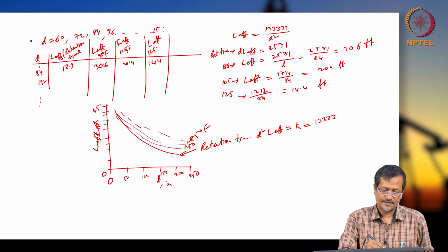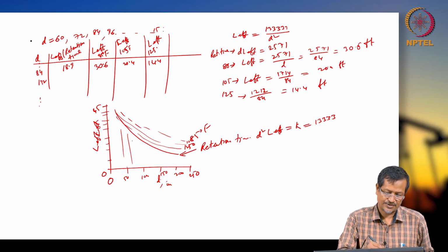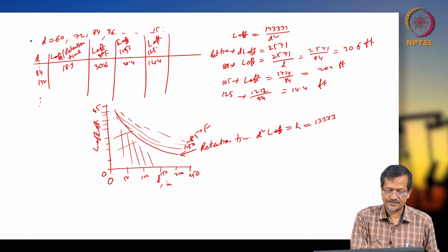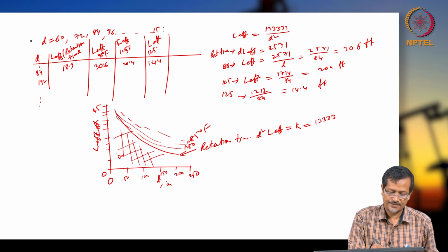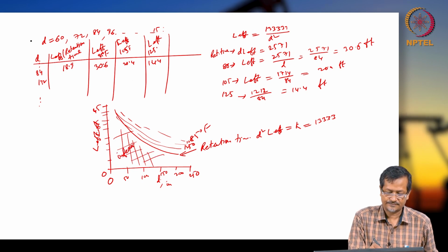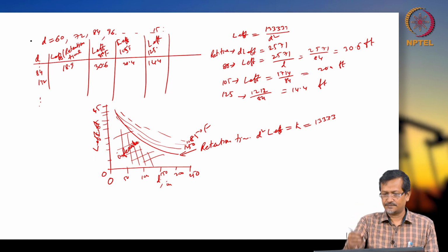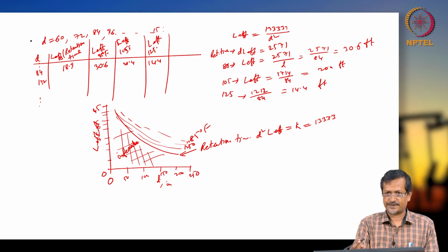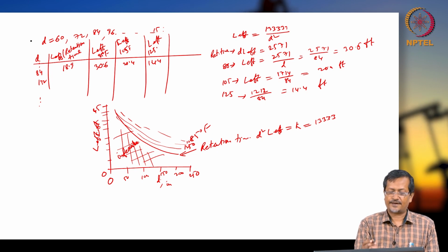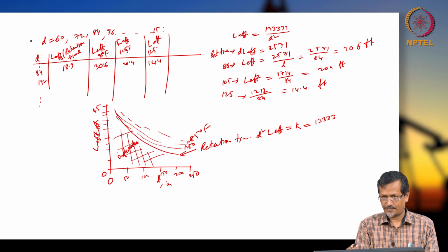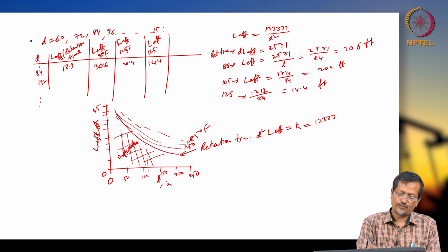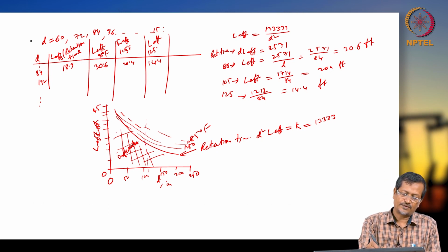So they are saying this area is infeasible, okay. Any data coming above this retention time curve is the feasible range. And diameter, if you are increasing diameter too much, separation will not help, okay. So diameter should be within this zone.